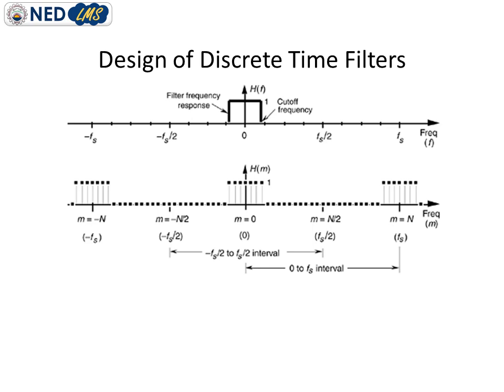But recall the concept we studied earlier. We have to look only at the unique range of the frequency, which is minus fs by 2 to fs by 2, or we can say 0 to fs. Or after learning the concept of FFT, we came to know that the unique frequency range or the spectrum can be counted only for the values of 0 to fs by 2, which you can also see from this discrete frequency response.